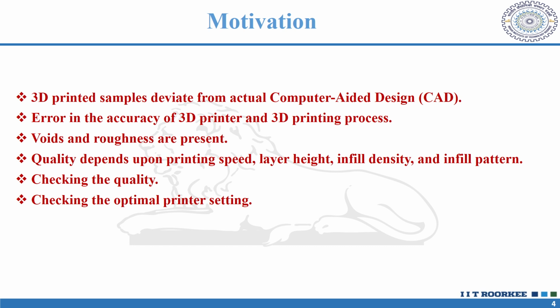The 3D printed sample carries defects, means there are voids present in the sample, and the location of voids coincides with the location of failure.